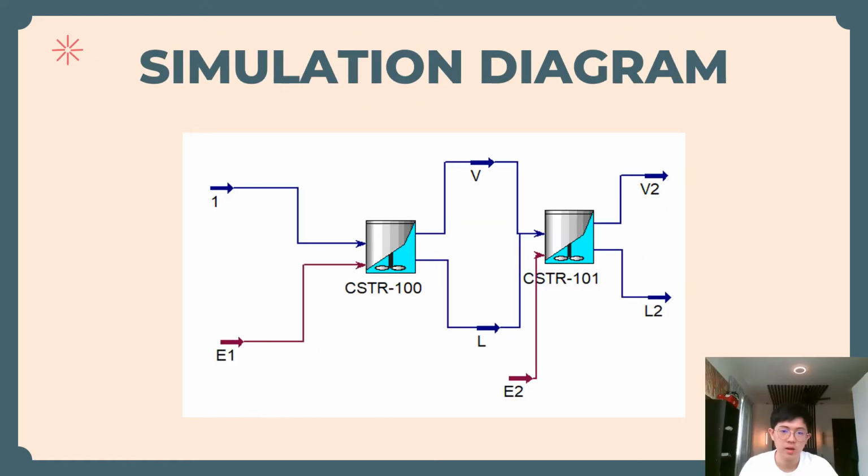Hello everyone, I'm Xiong Jazen, and today I will be explaining the simulation which we have completed through the Aspen HYSYS software. This is a steady-state reaction process which converts palm oil mill effluent into biogas. The parameters of the simulation are based on process parameters which were defined in the reaction engineering segment. The simulation involves two CSTRs and two product streams.